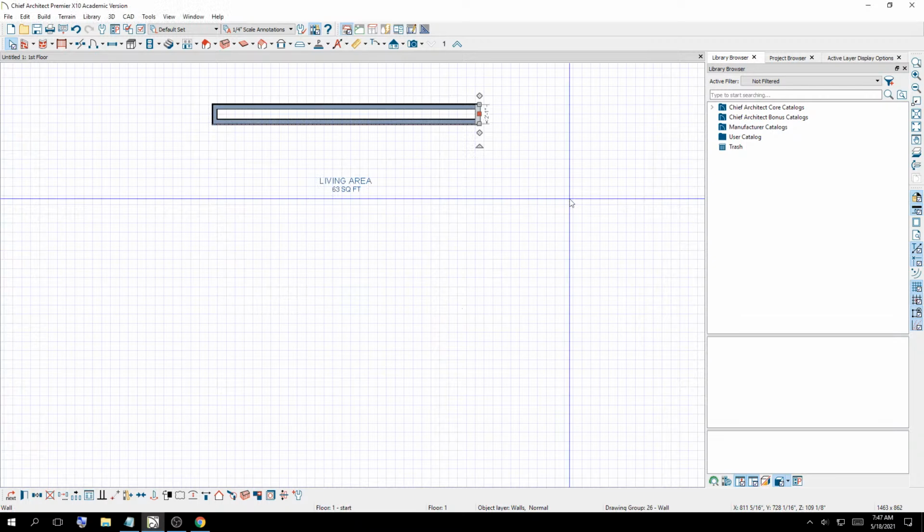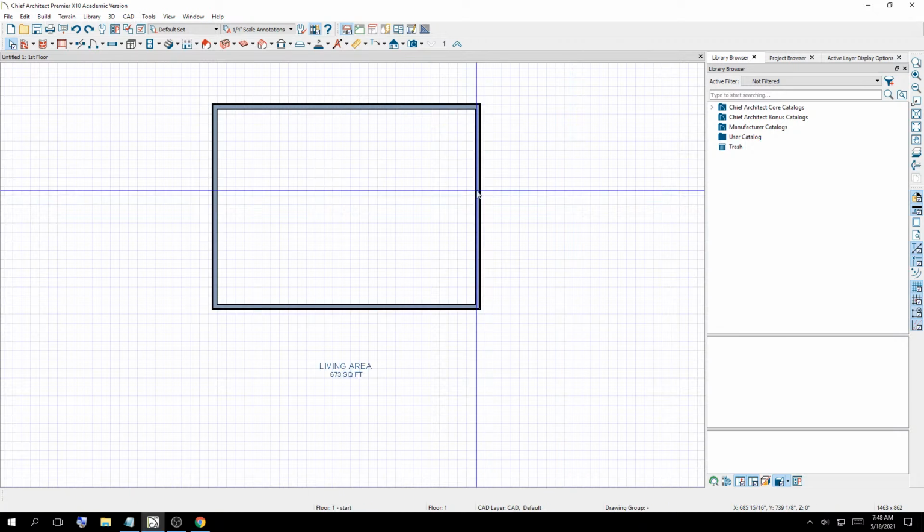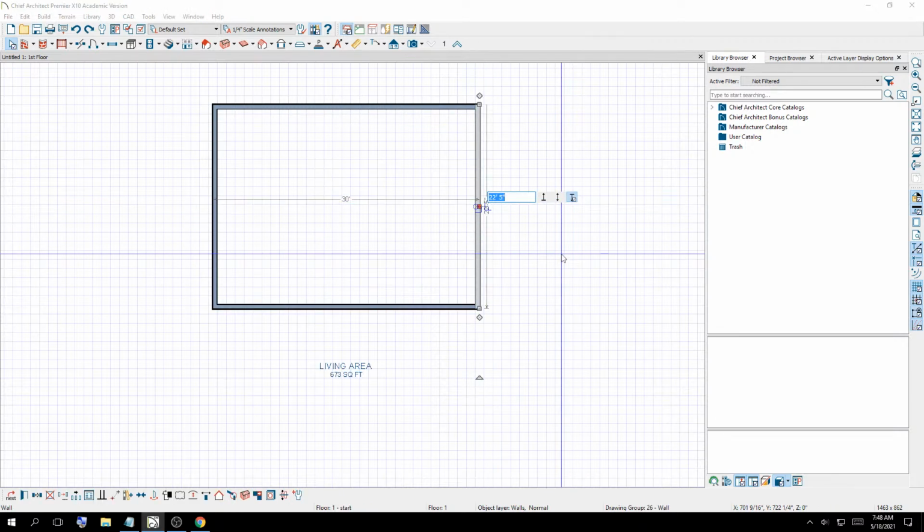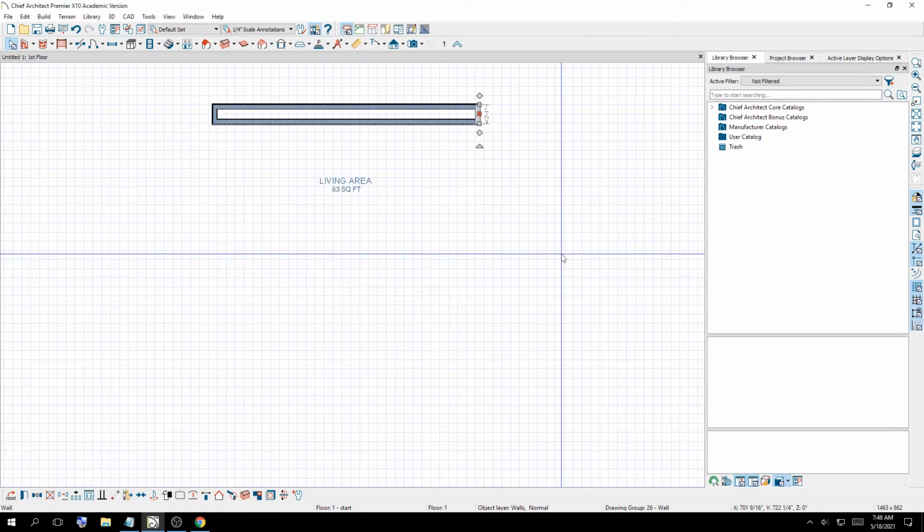So I'm just going to press enter, and you notice things changed quite a bit. So I put 25, but I didn't actually put the unit of measurement. And if you don't imply that you're creating feet by marking it with the apostrophe, it's going to automatically assume that it's inches. So we're going to hit Control Z and undo that. And I'm going to click here again, and once again, I just hit 25. That's going to go to inches.